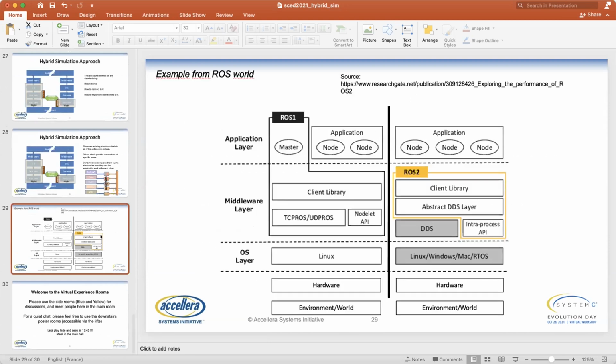I think what you see in various industries is that in robotics, what started 10 years ago or longer as just fun stuff is getting pretty serious. They made the move already from ROS 1, which had a certain architecture. They took the learnings and moved to ROS 2, and they made some fundamental choices. One of the very intriguing things I see in that framework is this data distribution layer called DDS, which is an OMG standard, a bit of an abstract communication protocol between different environments. And they use that as a foundational layer as part of ROS 2.